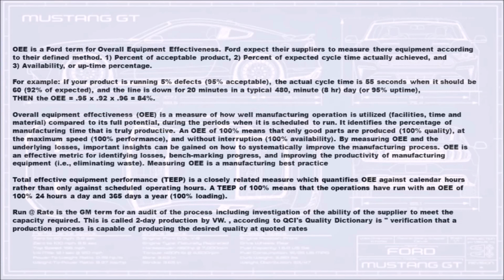Total Effective Equipment Performance, TEEP, is a closely related measure which quantifies OEE against calendar hours rather than only against scheduled operating hours. A TEEP of 100% means that the operations have run with an OEE of 100% 24 hours a day and 365 days a year, 100% loading.